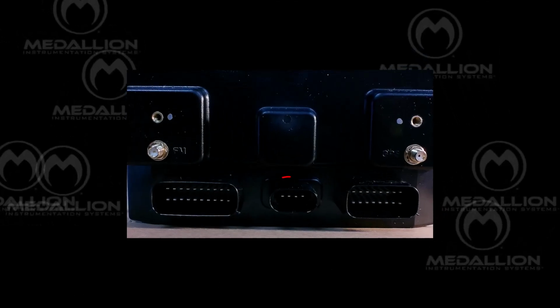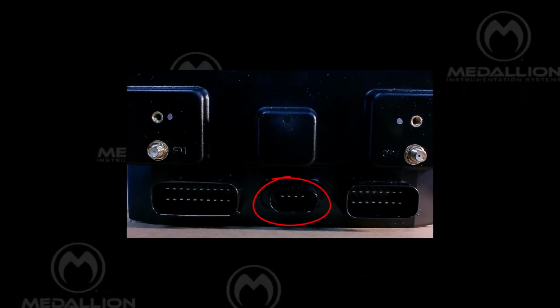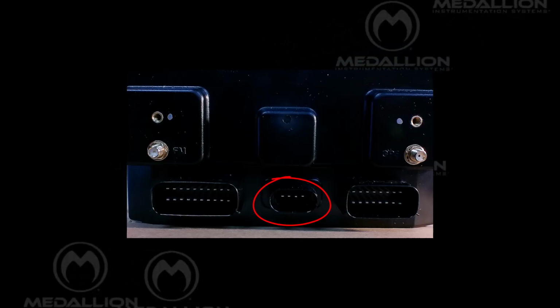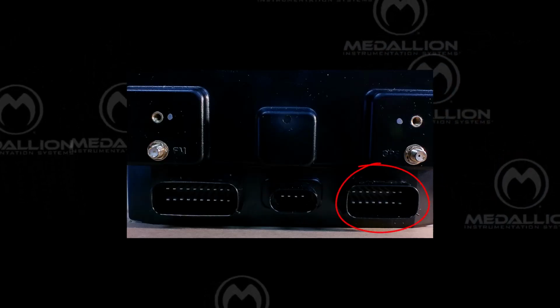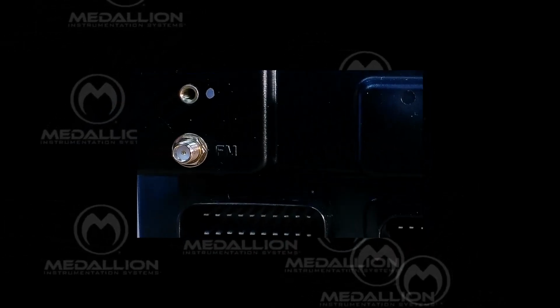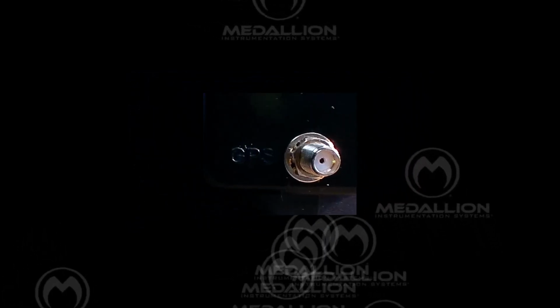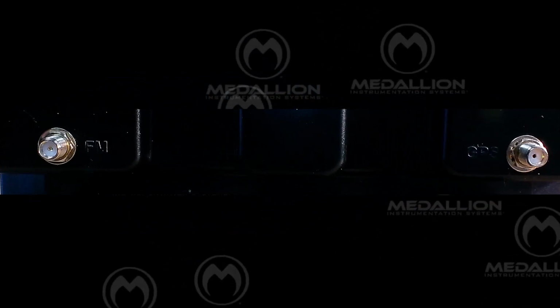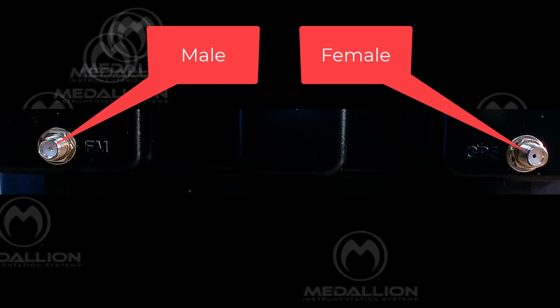The center connector is intended for the USB interface cable. This may have a cable connected to it that will allow you to insert your thumb drive for upgrading software. The right connector is a 16-pin connector primarily used for the radio. The left antenna connector, labeled FM, is for the radio antenna, while the right antenna connector, labeled GPS, is for the GPS antenna. Note that one antenna connector is male and the other female, preventing incorrect antenna connections.